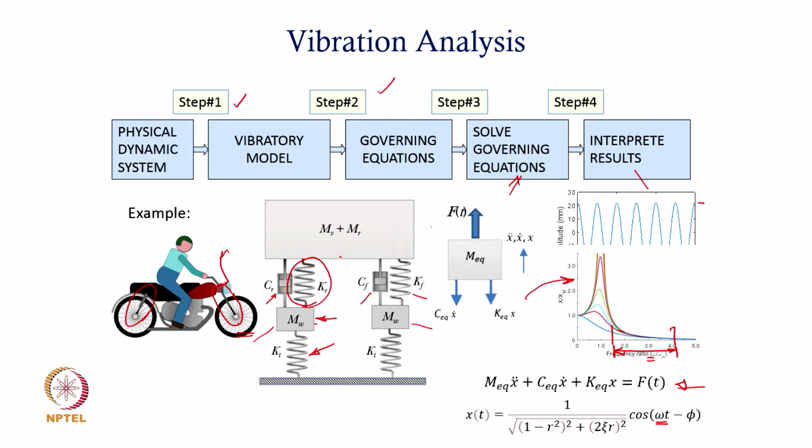Not only modeling these as different elements, but also finding out the appropriate degrees of freedom for each is very important. For example, you might have seen that if I suddenly brake this automobile when it is moving forward, it is not that the chassis just dips down and vibrates vertically, but you all have experienced this, that it will pitch, it will oscillate about an axis here.